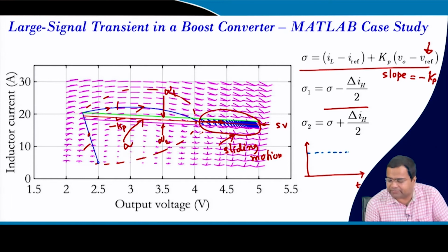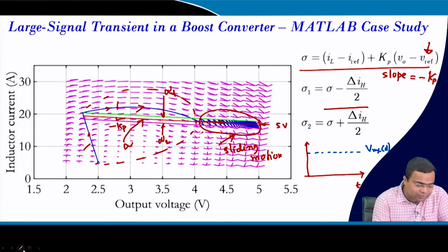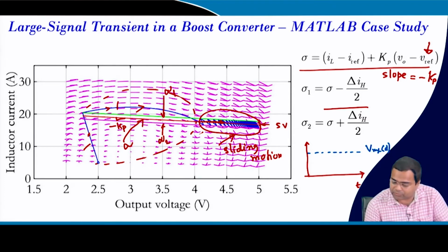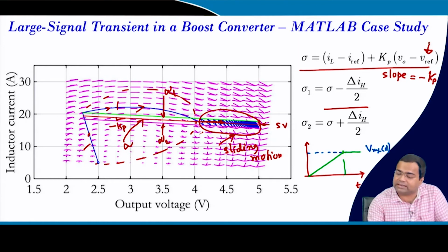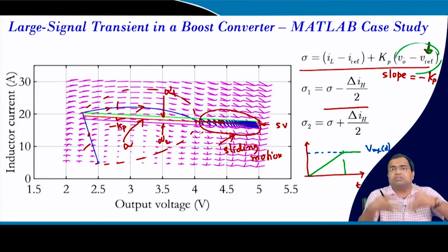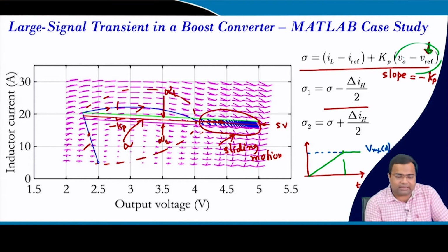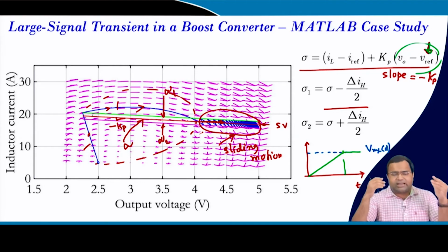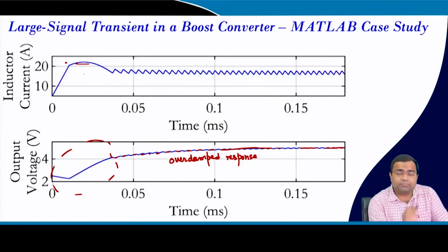So, this is our typical desired VREF. But actually, in order to get startup for a boost converter, we should raise the voltage like this and then keep it here. So, you need to put some kind of slew limit, so that it slowly increases, and the error, because your initial voltage is 0, slowly starts up. We have to take that into account, otherwise you will be bound to have such a large current transient, which is unavoidable, and it can damage your switch, because it requires a huge device rating to support such a high current overshoot due to the closed loop operation.